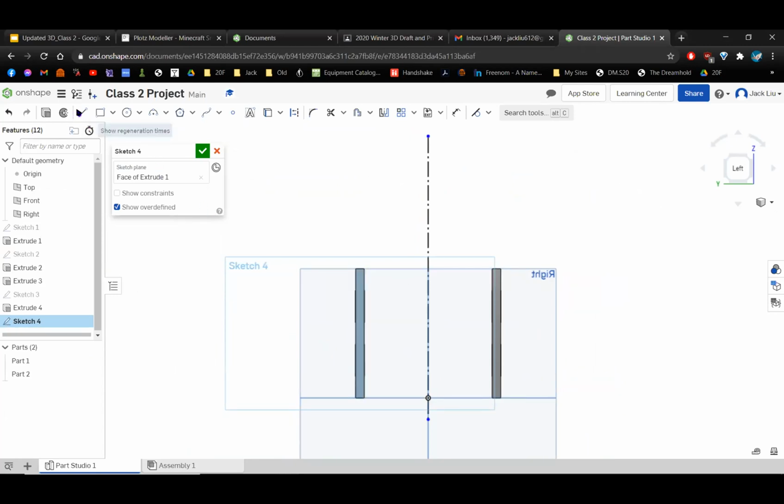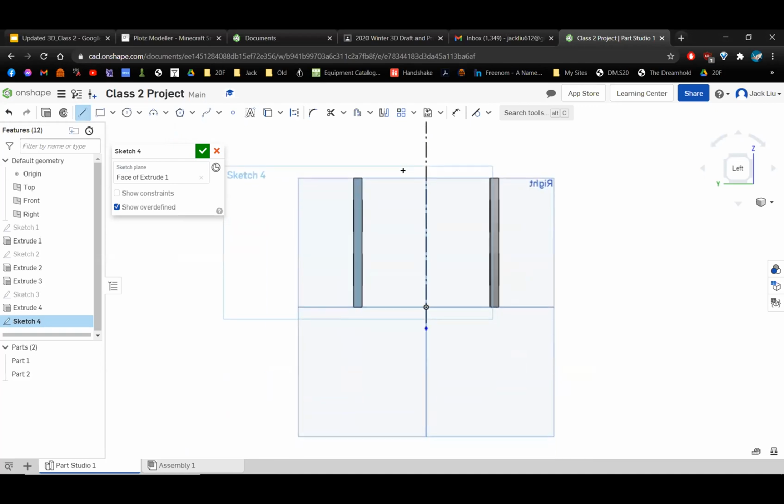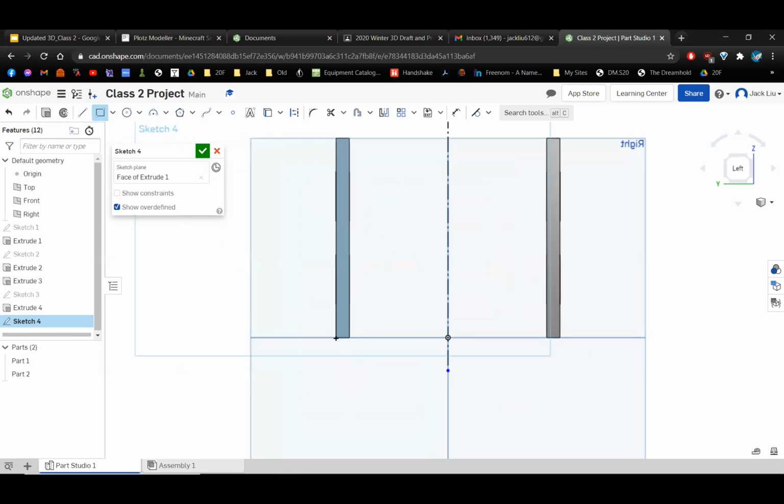But first, we're going to use our line tool, right? Line tool, we're going to mirror again, right? Or actually, maybe it's better if we do a rectangle and not do the mirror. So we're going to do the corner rectangle. And what you want to make sure, this is important, you want to hover over the corner of your house, the outside corner, not the inside, the outside corner. And you can see that it's surrounded by a yellow box if I'm hovering right over it. If you see that, click it, right?